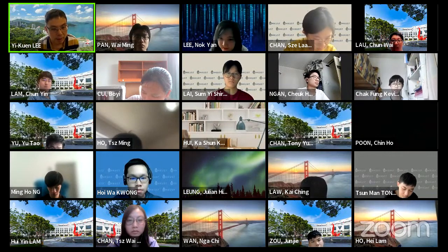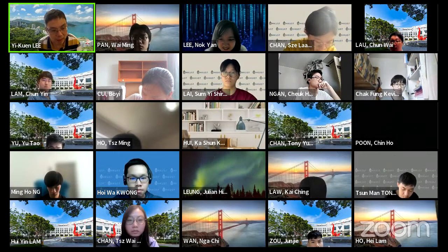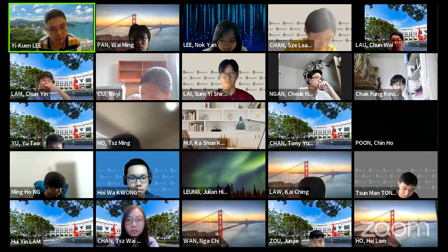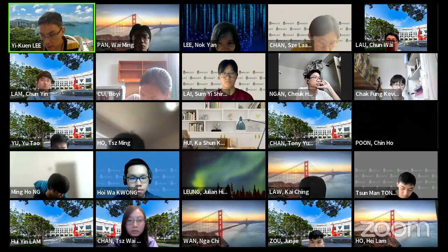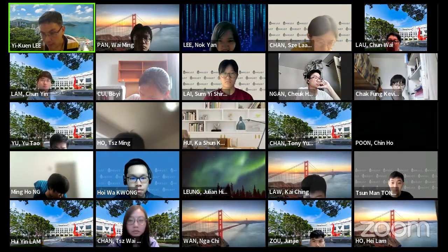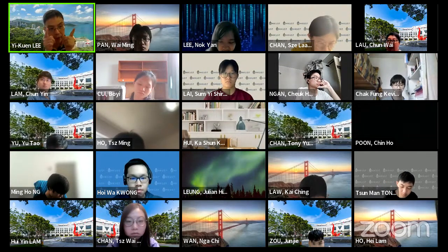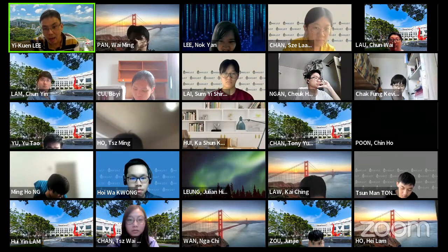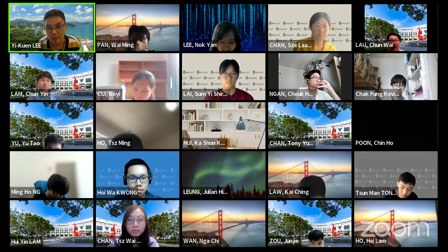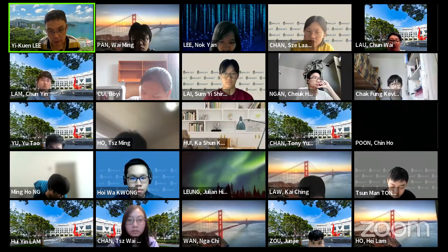I think because this PMV is derived from this kind of indoor environment, right? With about 1,000 people. They changed, as mentioned, different temperature, humidity, and air velocity. So yeah, very good. In this experiment they must have some airflow, but the airflow range has some limitation. If the speed is too high, they don't have experiment data, that's why they cannot give you PMV outside that air velocity range. Do you understand? So this tells you some limitation.